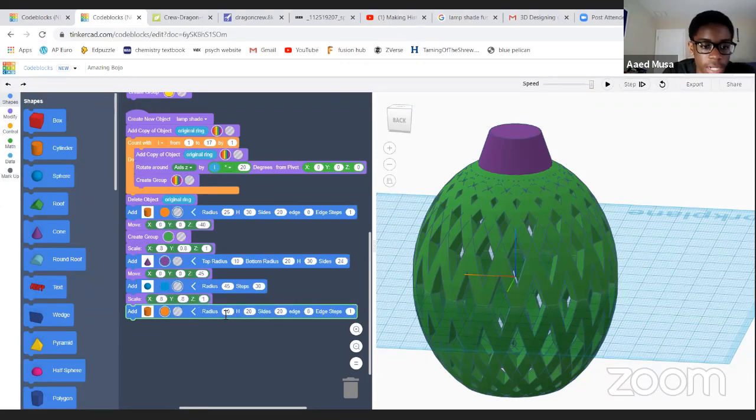And if we click on the arrow, we can have more settings. So the radius is going to be 2, and this is going to be really small because we want our hole to be fairly small, and we want our height to be pretty big. So we can make it like 50 and hope it covers the entire length of our cone on the top.